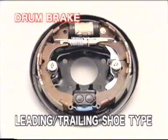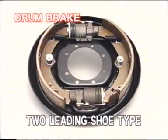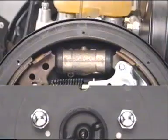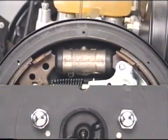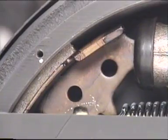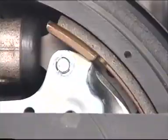Types of drum brakes depend on shoe installation or number of cylinders. For example, the leading trailing shoe type. 2 leading shoe type. And duo servo shoe type. The hydraulic pressure transmitted to the wheel cylinder forces the shoes apart. The lining installed outside the shoe rubs against the drum, revolving with the wheel, and produces brake force.